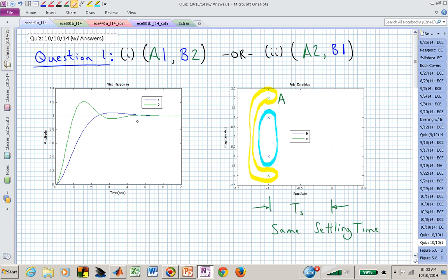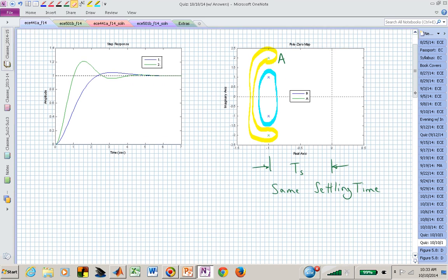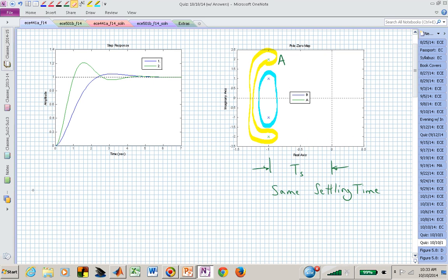We could actually compute that from what we've now learned about settling time behavior. The settling time for both A and B, in terms of the pole locations, both are into the left half plane a distance of 1. 4 time constants will be the same as 4 over sigma.